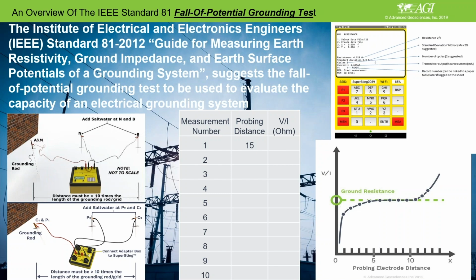For any overvoltage, grounding has to be done properly. Because if you choose a very resistive ground, in that case the grounding grid doesn't work. That means you cannot discharge your overvoltage, so you start damaging your system. Let's say if lightning hits your building, and it doesn't discharge directly into the ground, then it will damage it.